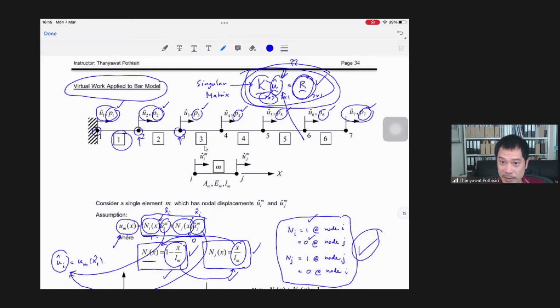And you would see that the displacement that you obtain from this system of equation would be an infinite set of displacements, so there are multiple solutions to this problem. The only way to prevent this kind of problem is to put proper constraints on your structure.